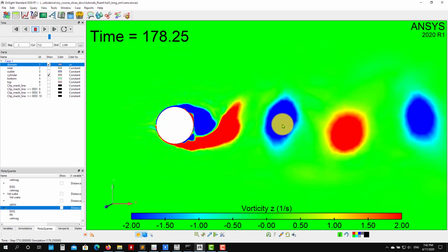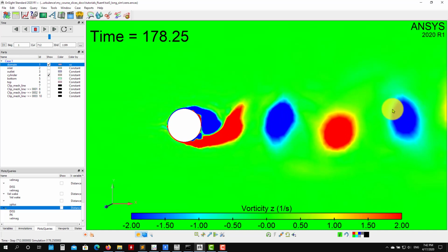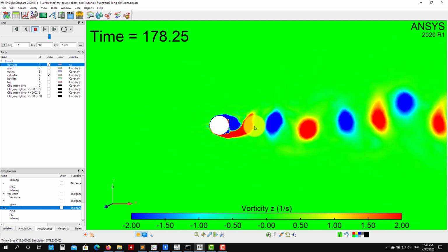Okay, so the idea of putting probes to measure the distance is that you can put a probe here, another here, here, and you see when this data decorrelates, it means that you are outside that vortex, and now you can get the dimension. So we're going to see that one in the statistical part. I don't do it very often in CFD because you can get it directly from here.